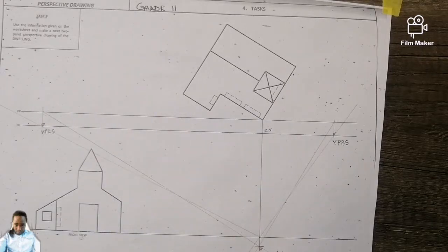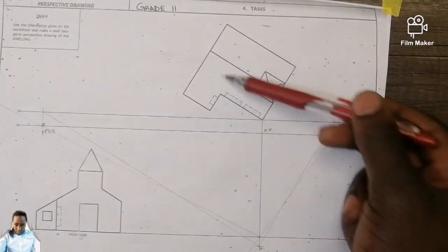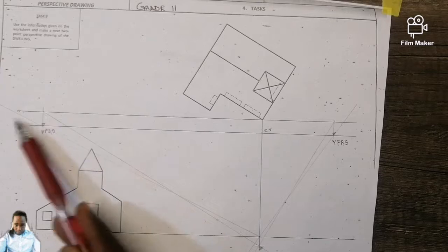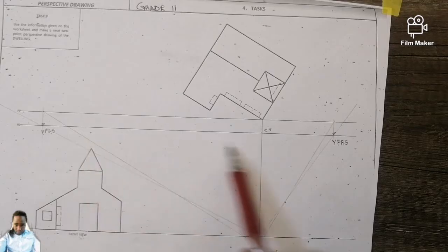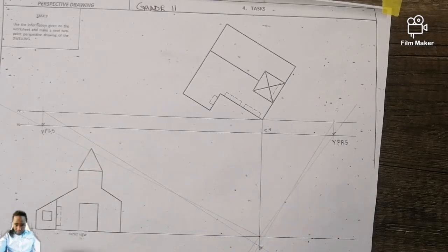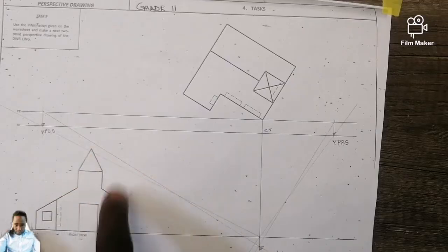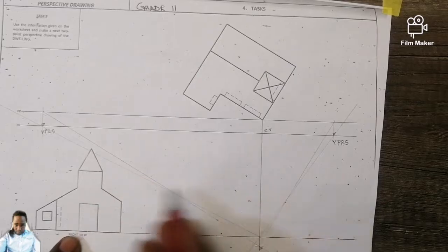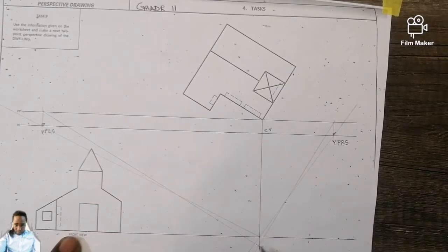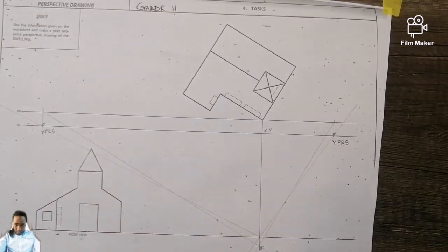Okay, so what we are going to do is project lines from the top view to the stationary point, once they touch the picture plane line, because this is the picture plane line. This is the horizontal level line, then this is the ground line, or GP, which stands for ground plane. You understand? They will go vertically down, but whatever point we take from our front view, we take horizontally, and once they touch the CVSP line, they will go to the vanishing point of your right or the vanishing point of your left. You understand? So let us go.